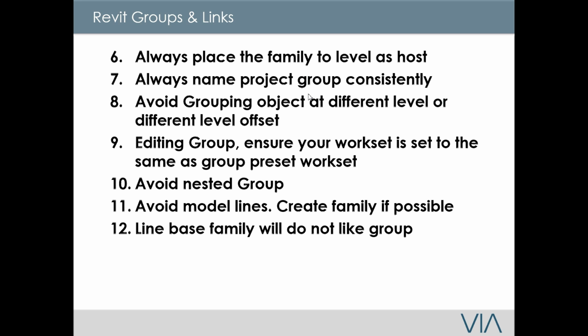What tends to happen in this case is that when you're working on a project, you may have certain worksets turned off. Let's say, for example, in my floor plan I do not want to show the furniture, so I just set my workset to furniture.